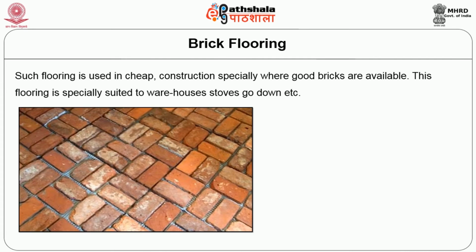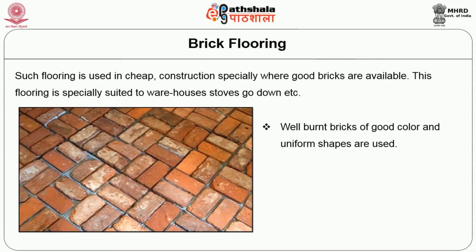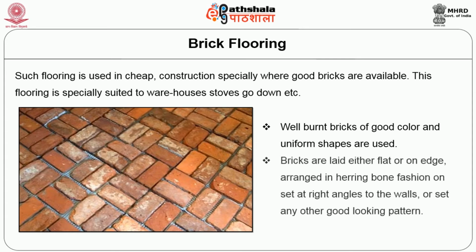Such flooring is used in cheap construction, especially where good bricks are available. This flooring is specially suitable for warehouses, towers and godowns, etc. Well burnt bricks of good color and uniform shapes are used. So bricks are laid either flat or on edge, arranged in herringbone fashion, or set at right angles to the walls or in any other good looking pattern.